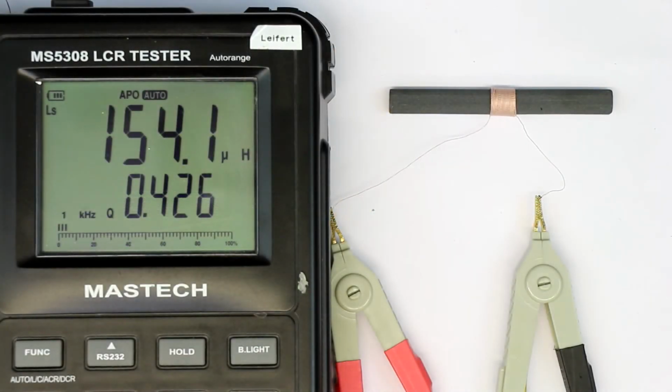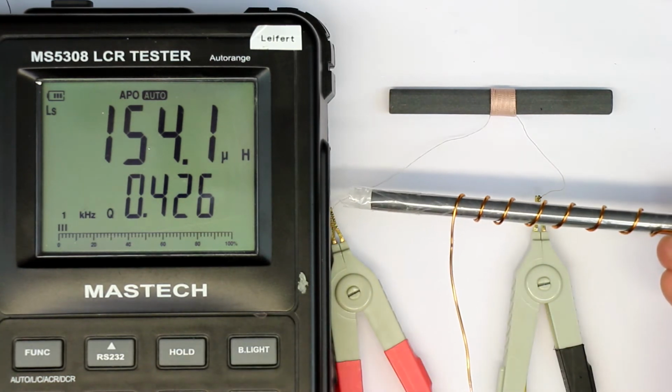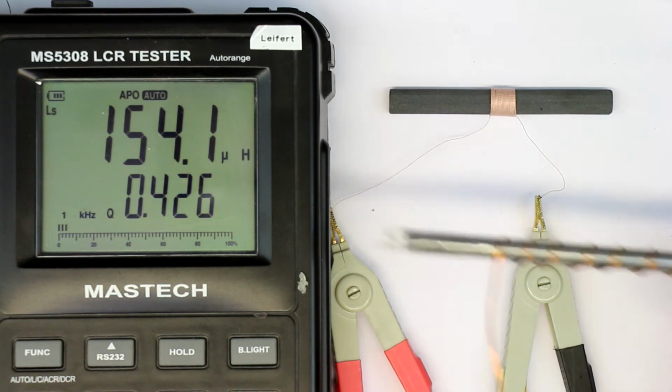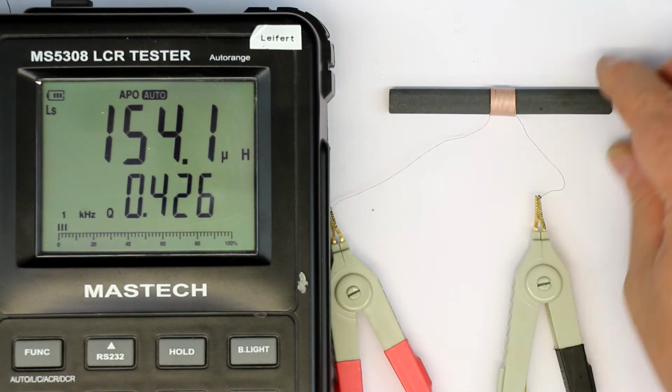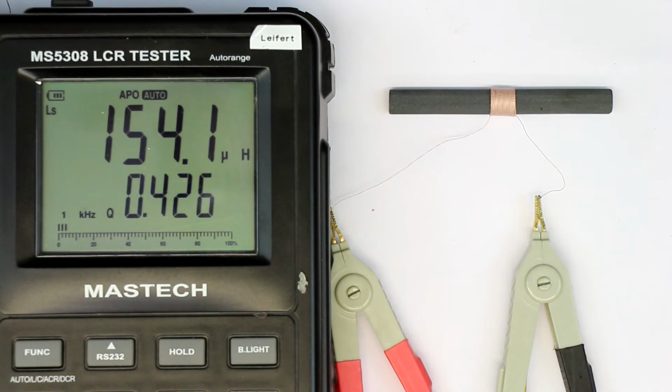So one final word about ferrite-rod or loopstick antennas. Why do we use them at all if they introduce additional losses? You know from the other videos that we already have to deal a lot with skin effect and proximity effect, and we have taken every measure to counteract them, like using thick wire, separating the single turns from each other by great distances, etc., etc. Now, why do we then use ferrite-rod material? Simply because antennas get much smaller.